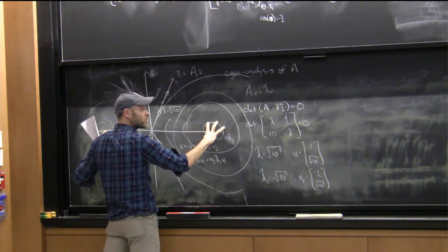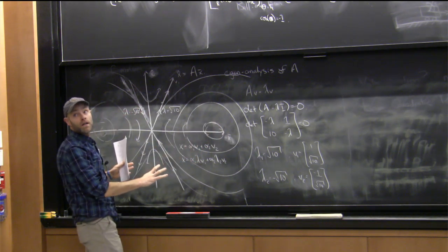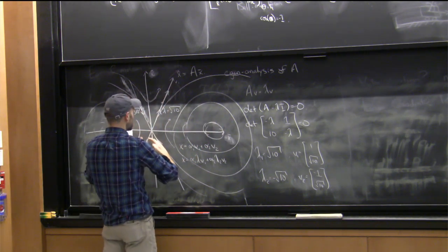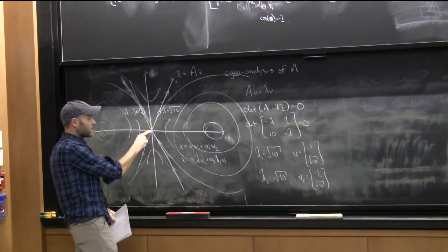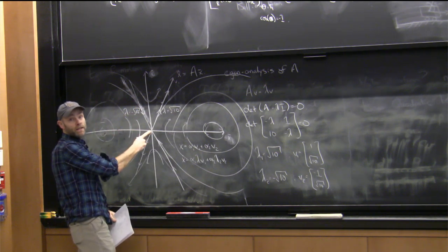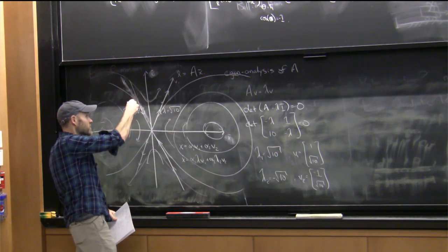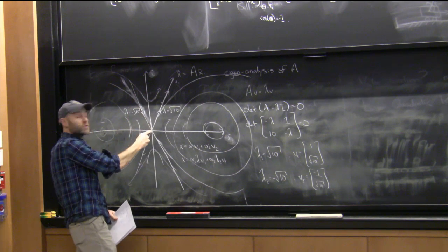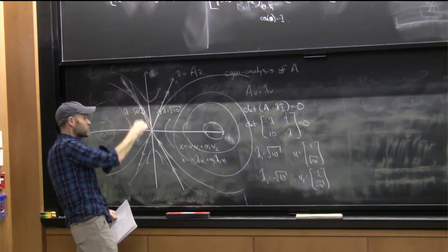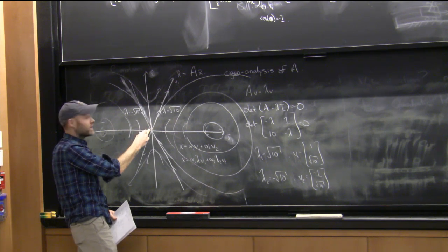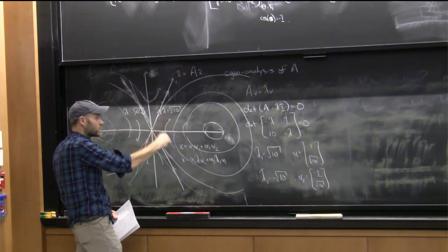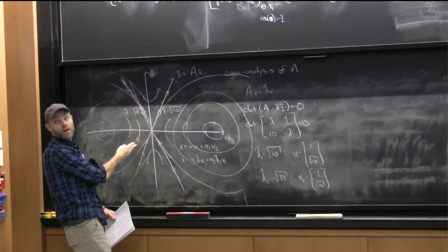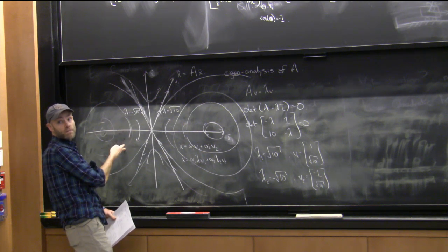But if I put the original pendulum dynamics on top, then what we can see is that this linear approximation is smack on right here at the upright, which is what you'd expect. The slope at which this orbit approaches that fixed point is captured by that eigenvector. Right? These curves are locally approximating the actual orbits around the pendulum, right?